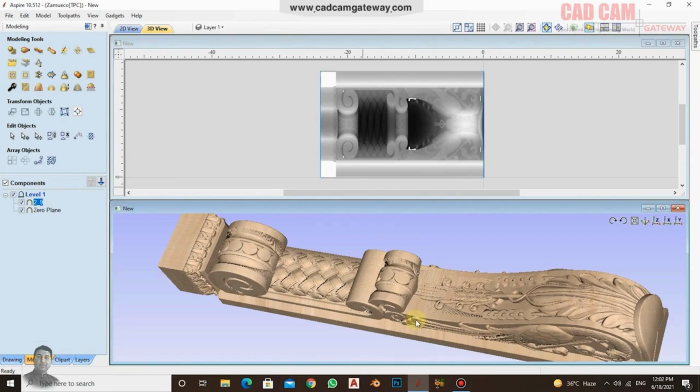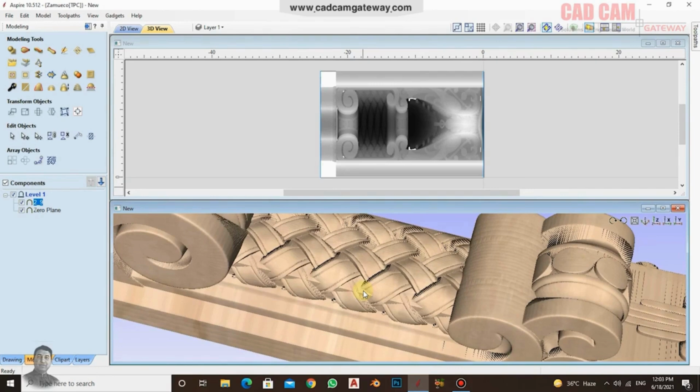Normally, what happens in our market here is that people use a motor tool, that is, a ball nose tool. The ball nose is basically used for three dimensions. So, the thing to understand here is that if you use a ball nose of one size, then the design's fine details can't be finer than that size. So, try to use a finer ball nose for work where you want good quality.